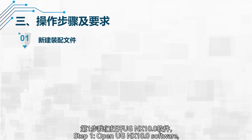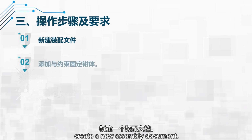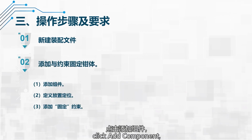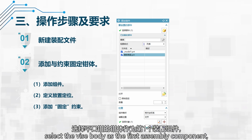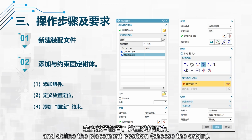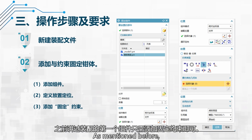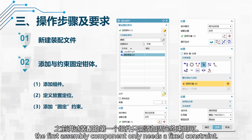Step 1. Open UGNX10 software. Create a new assembly document. Enter the working environment. Click Add Component. Select the Vise body as the first assembly component, and define the placement position. Then, add constraints to this Vise body. As mentioned before, the first assembly component only needs a fixed constraint.